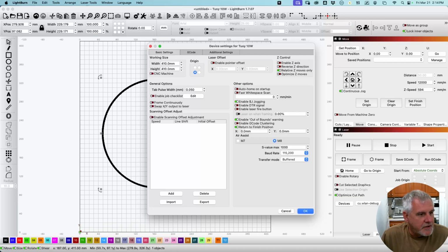This setting controls whether LightBurn sends a data terminal ready signal to the controller to start serial communication. Many programmable hobby level controllers, including Arduino based systems, use the DTR pin to reset the controller. LightBurn usually sets this value for you, but if your G-code controller won't communicate, toggling this may help. So you may or may not need that.